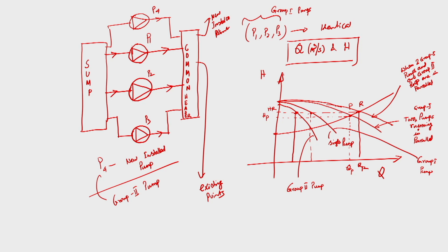My question is, in that case we assume that all the pumps are running connected in parallel. They will run if and only if all of them are experiencing the same system resistance. So, this is very important, we need to know. Whenever you are connecting pumps in parallel, each of them will run only if all of them are experiencing the same system resistance in which they are connected.